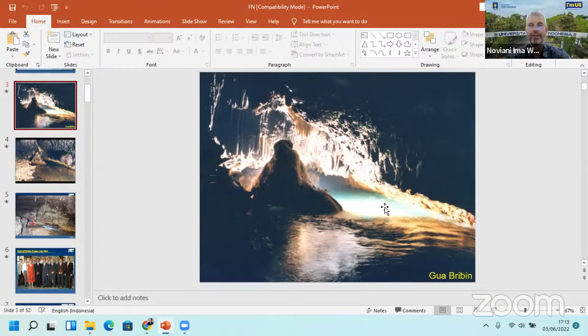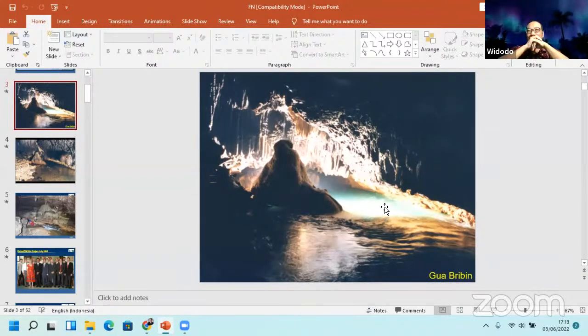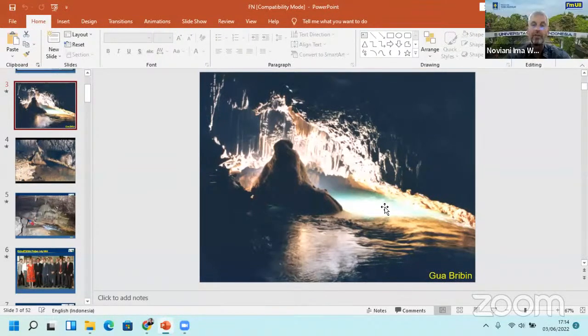So you're right. Karst is the only time when you really have groundwater rivers, and karst is only covering a small fraction of the surface. So most of the time, I would say 90% of the time, you don't have rivers, and flow takes place in either the pores or the fractures and fissures in rocks.